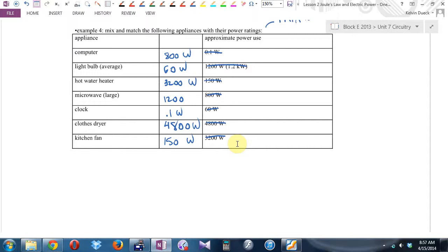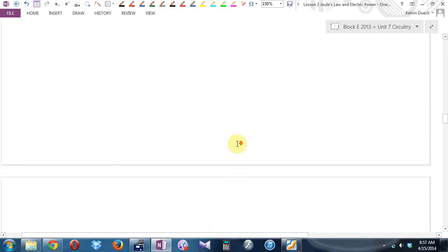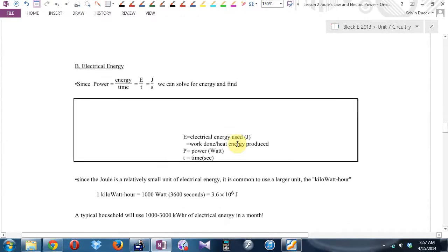But the other thing is, once the hot water heater is full, you're almost never draining the hot water heater and refilling it with cold water from scratch. It just trickles. That's why it takes several hours for a hot water heater to reheat. It must hold a couple hundred liters. Yeah, but we don't heat it very fast. It's designed to be basically a trickle heater, essentially. That's why it gets cold in a family when you have showers at the same time.